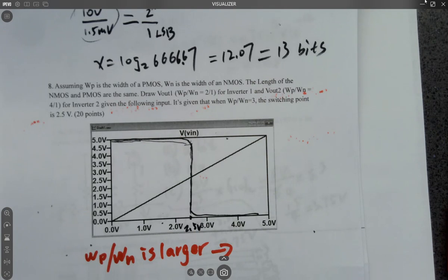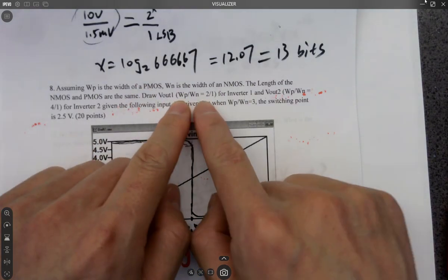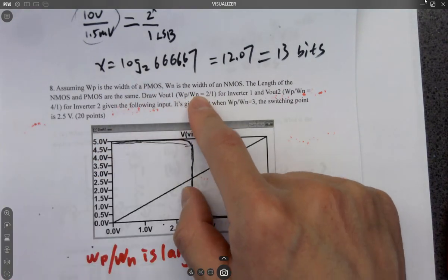Because we want to use the smallest length to define the dimension of the transistor, and then we change the ratio by varying the width only, but not both at the same time. Otherwise, it doesn't make sense to decrease the size down to 3 nanometers from 180 nanometers, when the cost is probably 1,000 times more. We just want everything to be smaller and faster, and that's the whole point. If we have the smallest length available, we're going to use it. So that's why we keep the length the same and only vary the width.